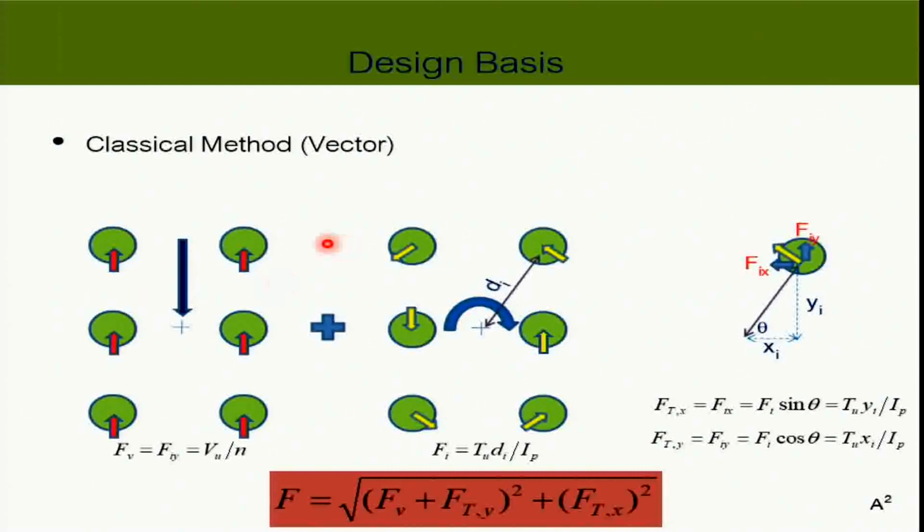So when you have the classical method, you can calculate the force acting on the bolt, say, by using this very simple approach. Simply the force divided by the number of bolts you have. So now you have this. See, we can use this because of that bolt group factor.